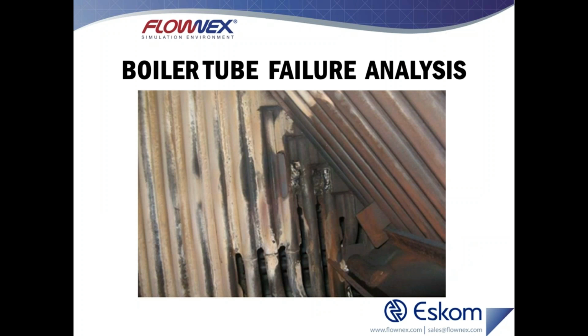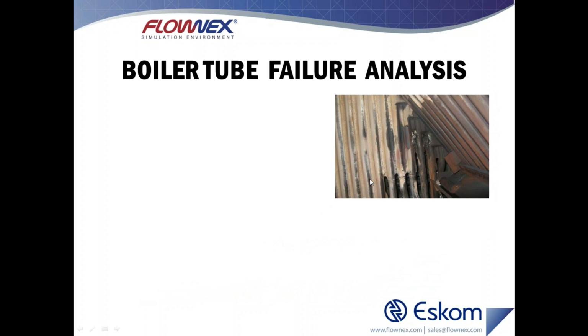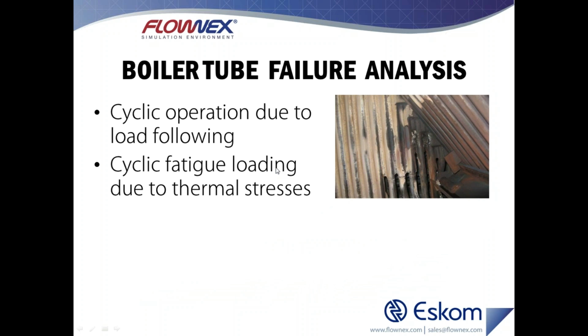All right, the next thing I'd like to talk about is a boiler tube failure. So this is slightly different to your traditional pipe stress analysis in the sense that boilers are many tubes all connected in parallel. This is typically not an application suited to most pipe stress analysis packages, so we'll be looking at an ANSYS mechanical link here instead. The particular picture you're seeing over there is a photograph of a boiler from a company called Eskom. They're the electricity supplier for South Africa, and this is a photograph of the bottom section of one of their boilers. This particular failure is happening because of cyclic stresses inside of the boiler.